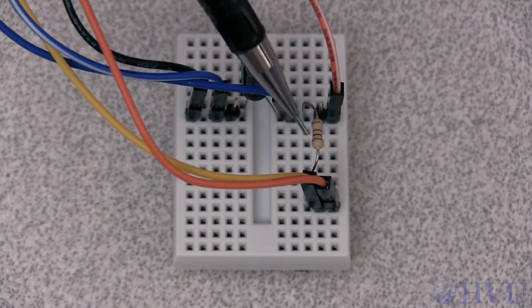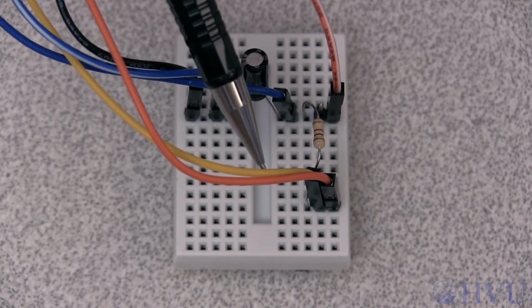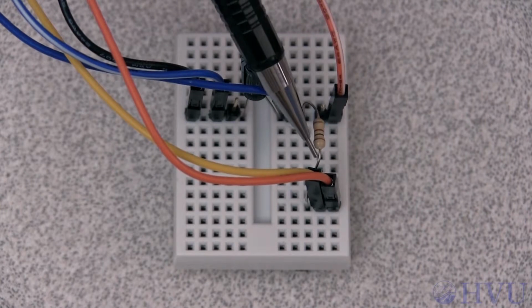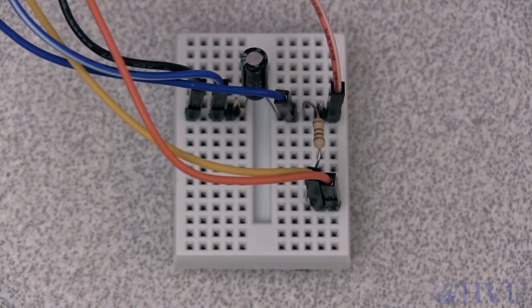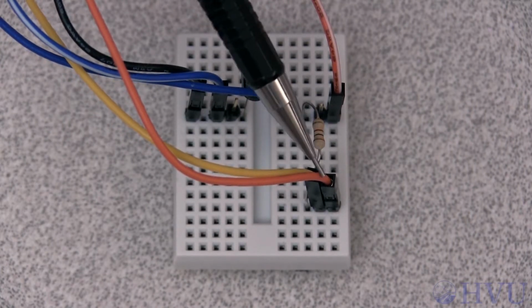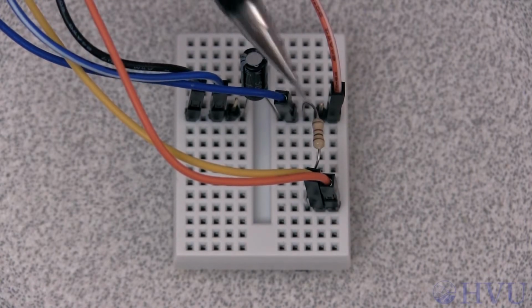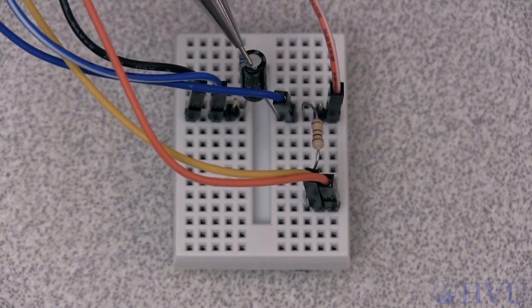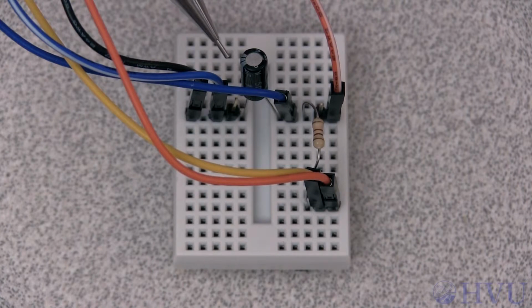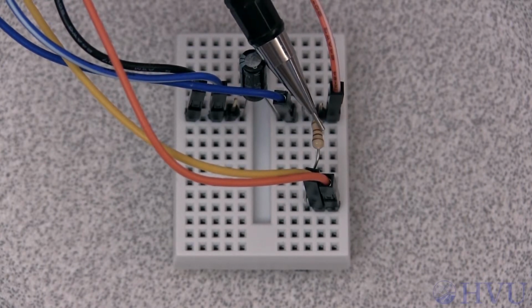This is my circuit. My resistor is here, my capacitor is here. I'm using channel 1 of the waveform generator, the yellow wire, to provide power to the circuit, and this terminal of the capacitor is grounded. Using channel 1 of the oscilloscope, the orange wire and the orange wire with a white stripe, I measure the voltage across the resistor. Using channel 2, the blue wire and the blue wire with a white stripe, I measure the voltage across the capacitor. The current through all of the elements will be determined using a math channel to divide the resistor voltage by the resistance, which in my circuit is 100 ohms.